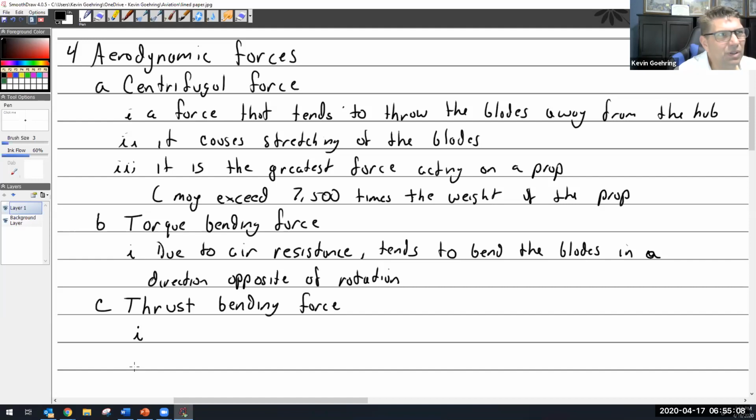Okay. We're going to talk about some of the props here, and they do product improvements. It's funny when you talk to prop shops and the things that happen to these props, you just shake your head. That's one of the big things about being a mechanic. You have to be so careful with propellers, because if you do something slightly stupid and have to send it in for something like a reseal, like you use the wrong grease, or you put too much grease in it, you can't fix that. You have to send it into a prop shop, and they're going to say, okay, we've got to do a disassembly, clean, and reassemble.